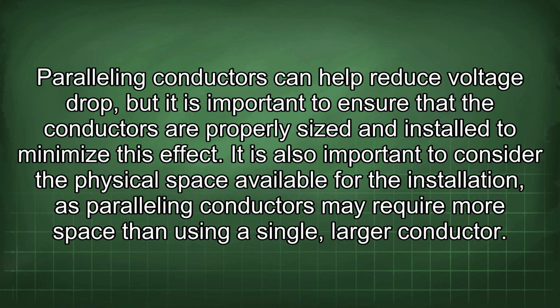Paralleling conductors can help reduce voltage drop, but it is important to ensure that the conductors are properly sized and installed to minimize this effect. It is also important to consider the physical space available for the installation, as paralleling conductors may require more space than using a single, larger conductor.